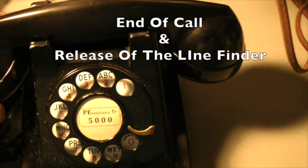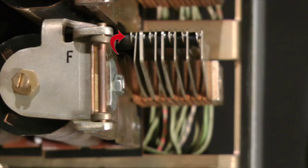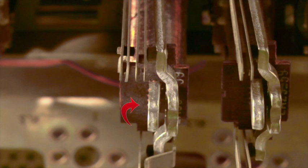At the end of the call, when the calling station hangs up, the loop through the calling telephone is opened, which triggers the release of the entire switch train. When the sleeve ground coming from the first selector is removed, the F relay releases, and the CO relay in the line circuit also releases, making the calling line appear idle to incoming calls.